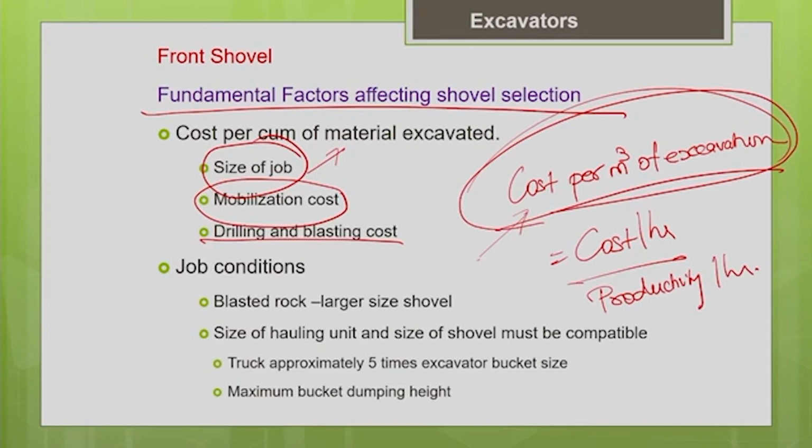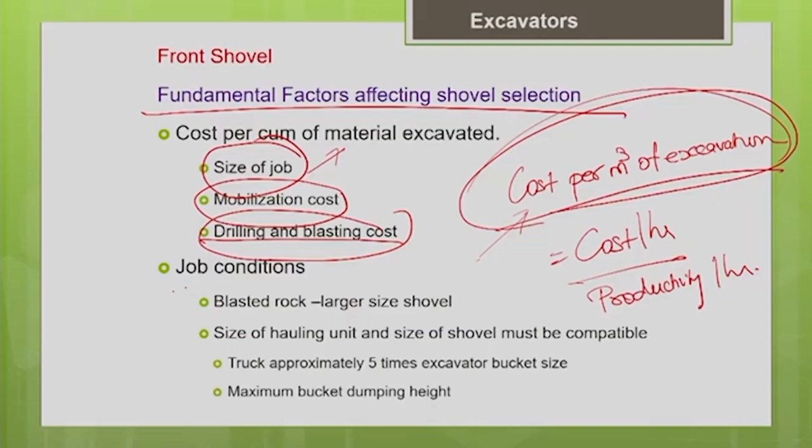Because your bucket is bigger, it can handle bigger pieces of rock. So that is the advantage of going for the bigger machine. It will reduce your drilling and blasting cost. So all these things you have to work out the economics and select your machine. Okay. So apart from this, the other job conditions which are going to affect your selection is, particularly, as